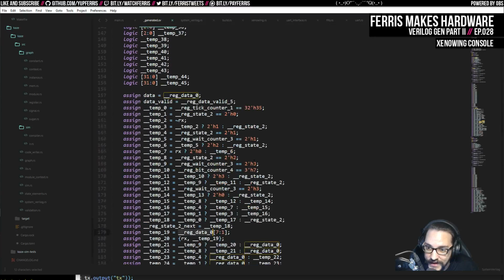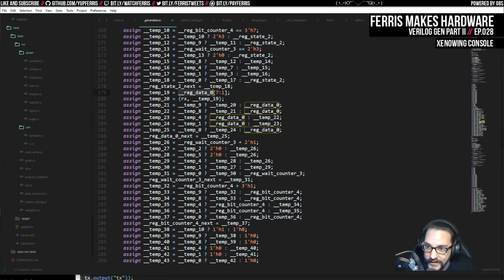If you take this data register and you only take some of the high bits, but not the very high one, and then you shift it, and then you truncate it to 1 bit, this 1 bit ends up staying constant. It never changes. Its value actually depends on what it was at startup, I think. But anyway, the whole register ended up getting optimized away, so I was never able to find it, which was kind of annoying to debug.